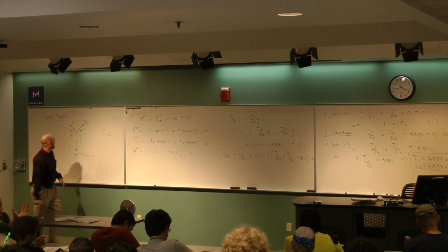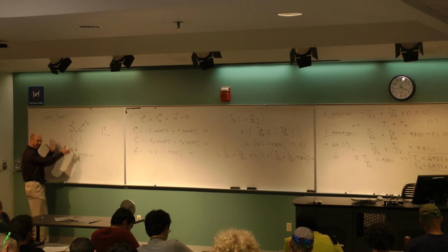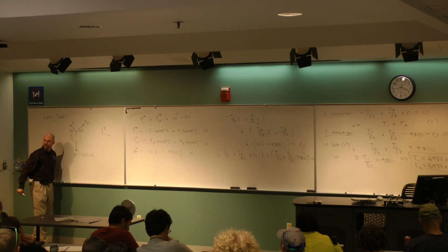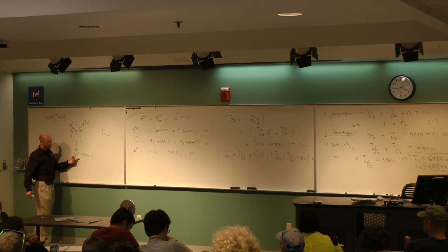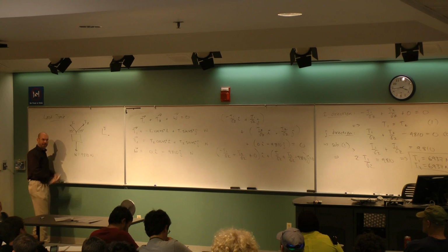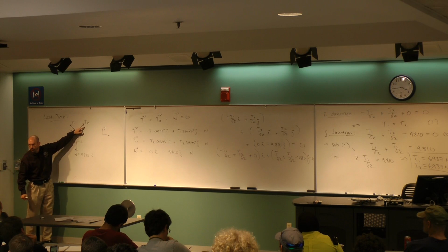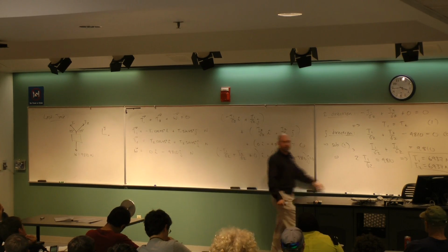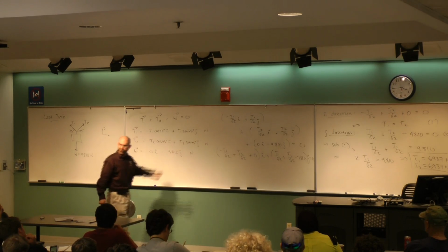All right, so the point is, again, I could have taken this problem, and if I had some high school physics and I had a sense of how this worked, I could look at this and say, well, the x components have to be the same, and they balance each other out, and then the y components have to add up to give me w. And in one calculator punch, I could probably look at this and go, T1 sine 45, this is still T1, so times 2 equals this, and solve for it, and I would be immediately at this number. So this is clearly a problem that doesn't need the rigors of this approach.